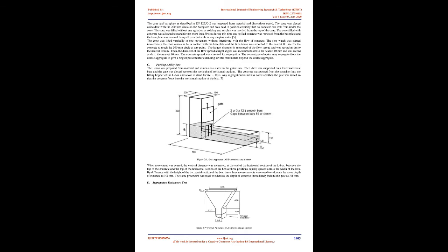Mix design was carried out for the concrete grade M20 as per IS 10262:2009 and IS 456:2000. These mix design principles result in concrete that, compared to traditional vibrated concrete, normally contains lower coarse aggregate content, increased paste content, low water/powder ratio, increased superplasticizer, and sometimes a viscosity modifying admixture.